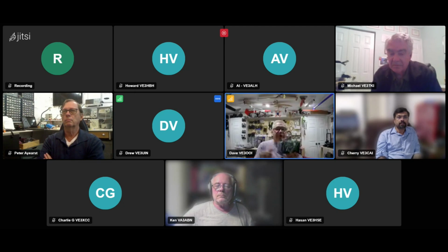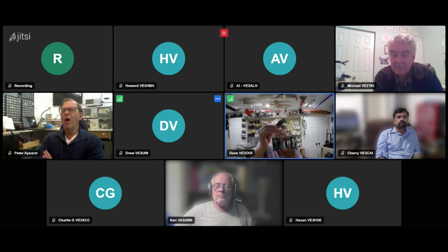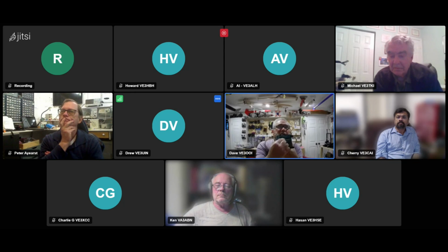All these connectors are just connectors going between the boards that are not run on the bus, and it runs off of an SD card disk. The SD card plugs in there, and it boots CPM off of that disk. CPM's a really, really old operating system. It's got RAM, ROM, memory, a clock, and I/O. Then at the front, you can see all the LEDs here.